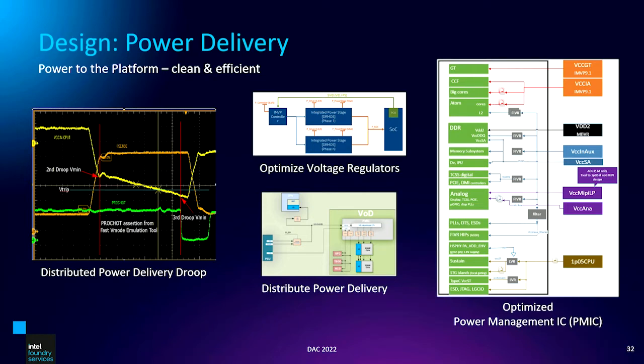The good news is that if we optimize chiplets by creating, for example, special I/O die with a thick oxide, that enables us to, in turn, create a special voltage rail for that die, which can accommodate the higher voltage. Correspondingly, as we get to logic die, which are logic-optimized, we can lower the voltage of the input from the power delivery, and we can do more fine-grained power management.